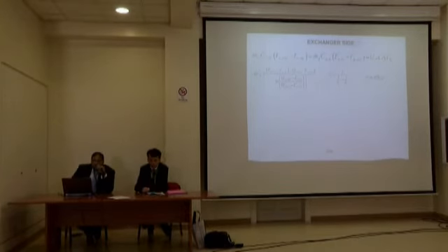Now, if we look at the first law of thermodynamics in the energy lost in the exhaust, we can relate the energy loss in the exhaust to the mass flow rate of gas and the temperature difference. With the mass flow rate of gas already calculated, we can calculate the two main parameters which are input parameters to the first set of governing equations: the mass flow rate of gas and the inlet temperature of gas to the heat exchanger, or the temperature of the exhaust gas.